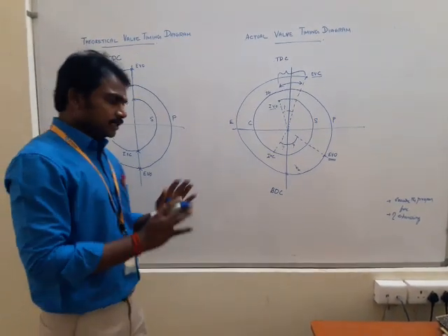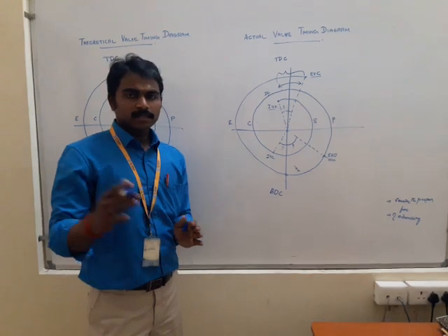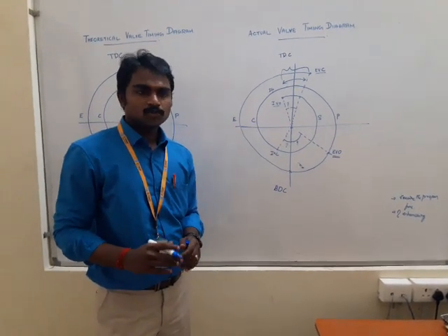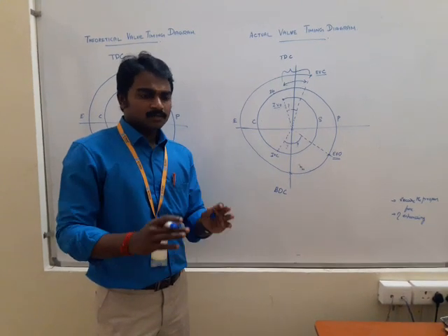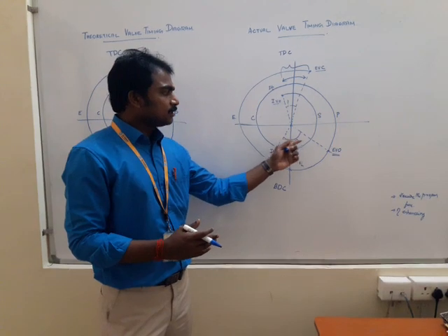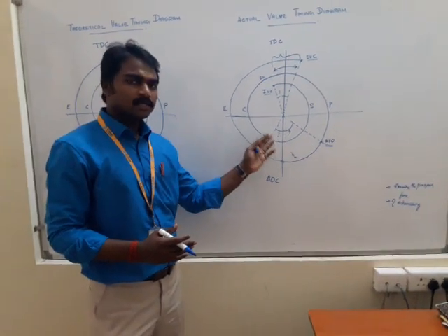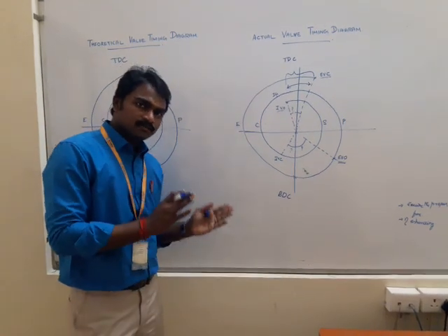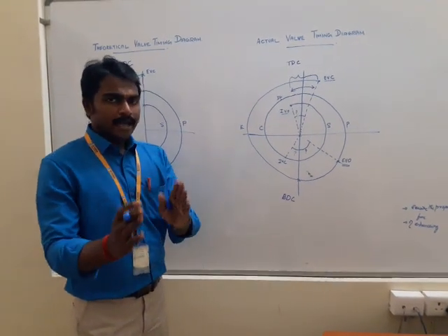Next, in the engine, we will see the experiment. There you are supposed to measure the circumference of the flywheel, through which we estimate the angles at which the valves open and close. For that there is a conversion from circumferential length to angle.